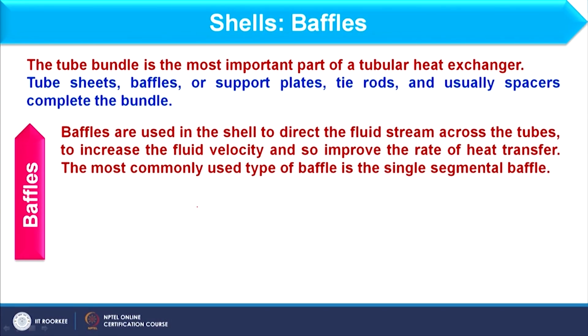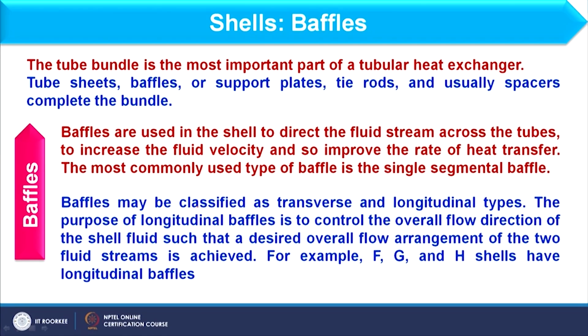Now, what is the purpose of baffles? We have already discussed that it basically directs the fluid on the shell side, okay, and depending upon the baffle design, we can control the pressure drop, we can control the heat transfer on the shell side. So, we will discuss different types of baffles. However, the most commonly used baffles are single segmental baffles, right. Now, as far as the position of baffles is concerned, these are of two types, okay. If you remember TEMA F shell or split flow shell, so in that case what you have observed?